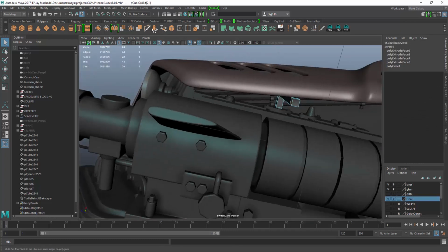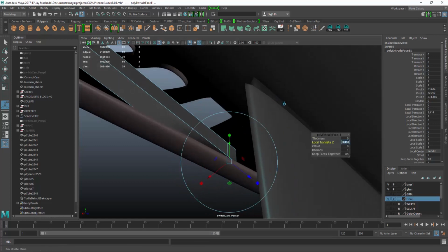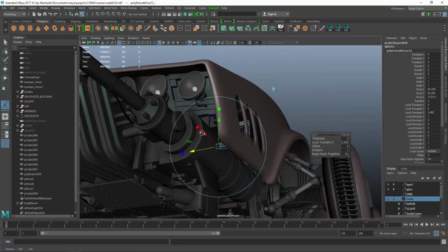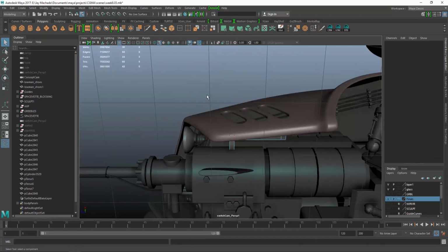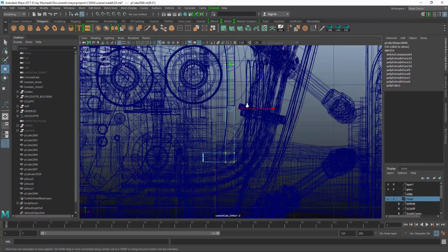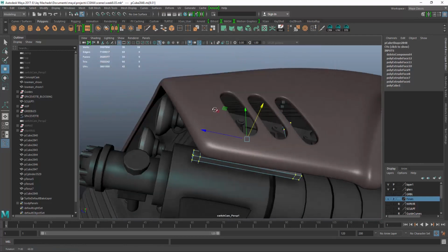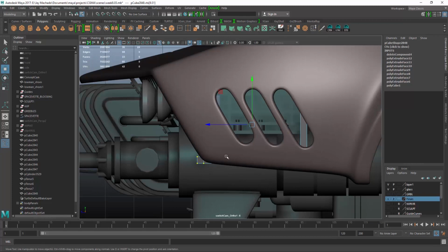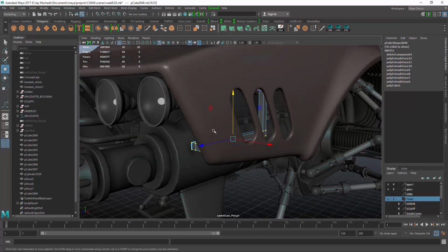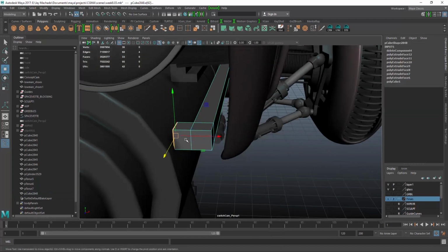So I'll pull this face forward, and again 2.25, and now I'll pull it in this way and just go ahead and delete the end. And I think I'm going to pull this forward, but I want to pull all these verts on the side of the pipe in so they're not crashing through the fender. And then I think I'll also pull this part up, and we'll intersect it kind of with this top area on the pipe. And grab that edge and crash it through.